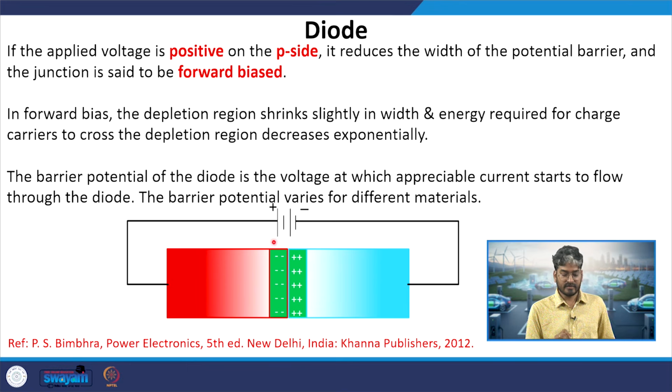The barrier potential will decrease, the carriers will be able to cross the junction, and current will be established in the device. Whenever a finite positive voltage is applied across the diode, it starts conduction, and if we neglect the onset drop of the diode, it behaves as a zero resistance path, and current flows freely when the diode is forward biased.